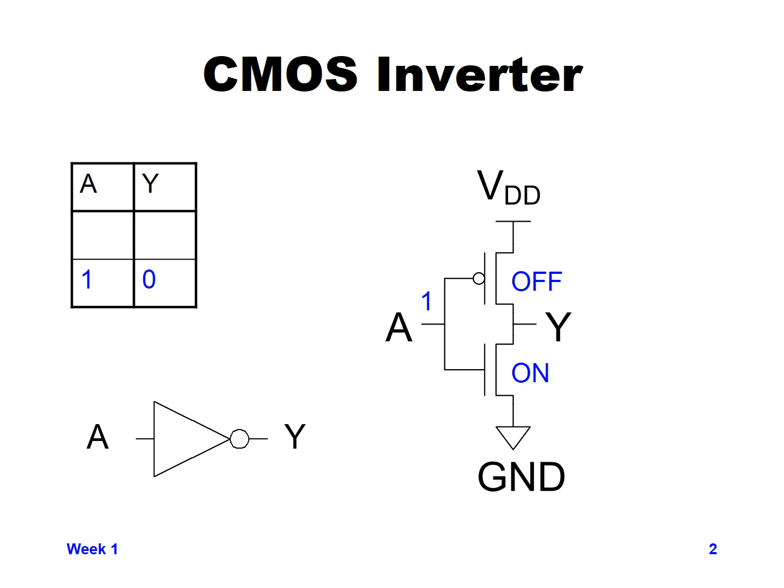And so an input of 1 causes an output of 0. Now if on the other hand our input A is connected to 0, this will cause the PMOS device, from our previous couple slides, to be turned on as a switch and the NMOS device to be turned off. This now means that our output Y has a direct connection to VDD and no connection to ground. So Y will be pulled up to VDD, which is a logical 1 value in the circuit.